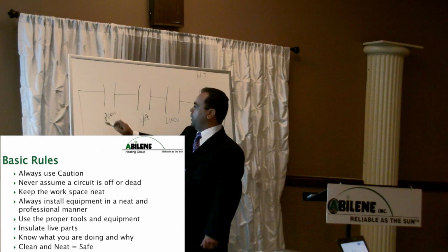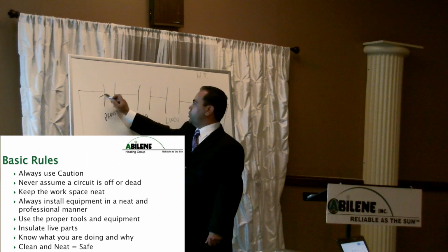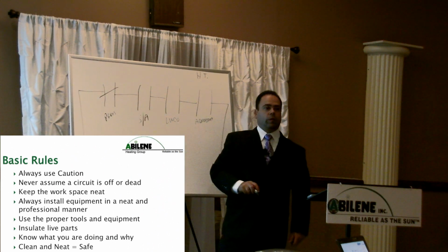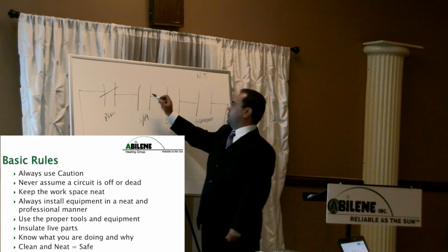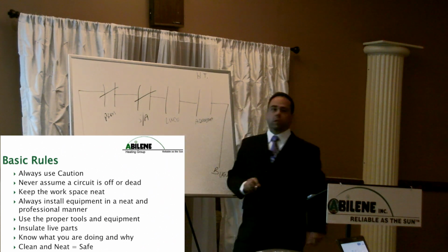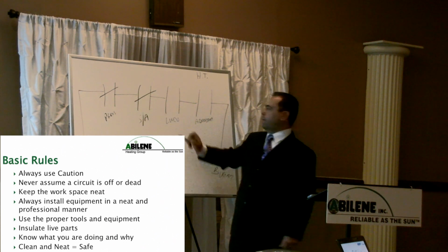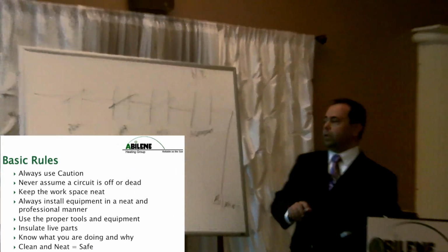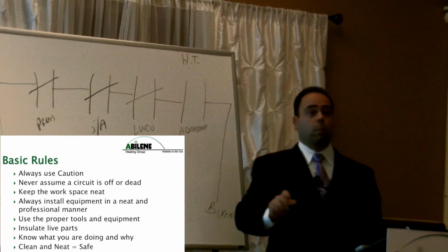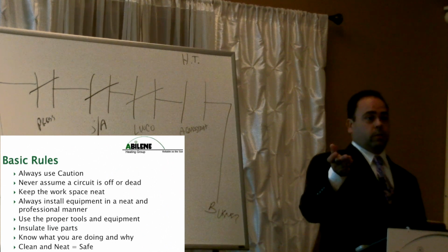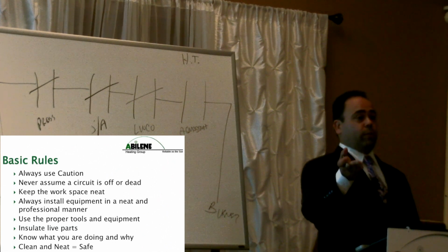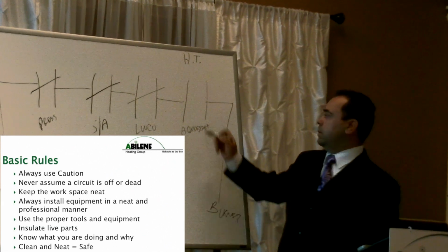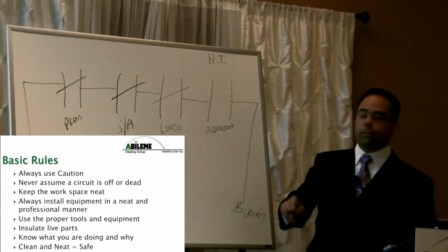If the pressure is below a certain level, this switch is going to be closed. If the burner's not smoking, this switch is going to be closed. If the boiler has the right amount of water in it, that switch is going to be closed. If I need more water temperature, or the aquastat is set at a certain temperature and I didn't make that yet, this switch will close.